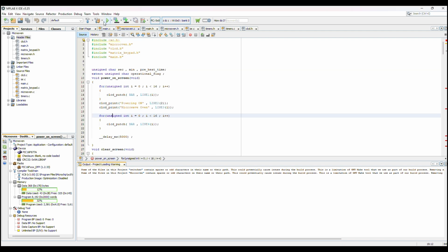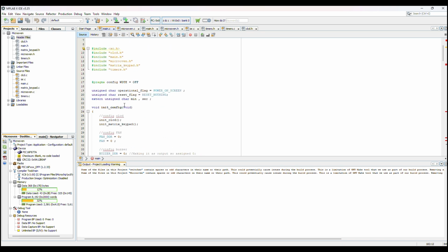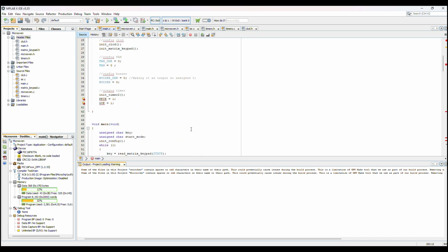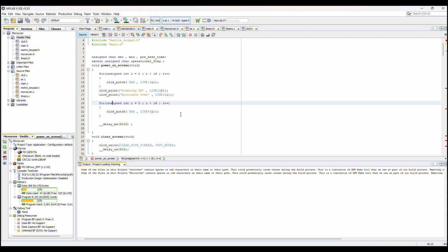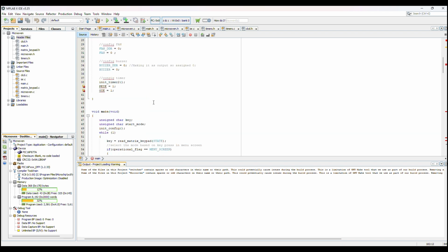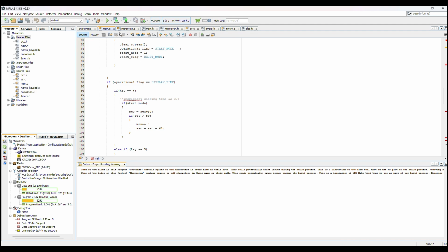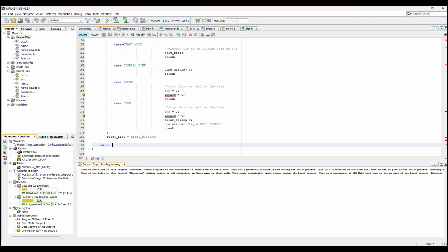The main.c file is the main file of this project, which includes all the features and what the micro oven should do, and the definitions of the functions involved in the main file are defined in the microoven.c file. Basically, the main.c file contains the code which allows the user to select the cooking modes, set time and temperature, and perform starting, pausing, and stopping of the oven operations.